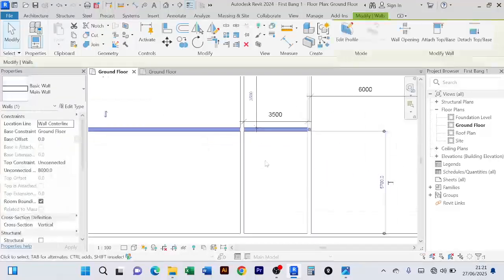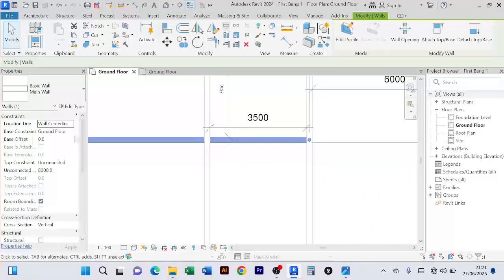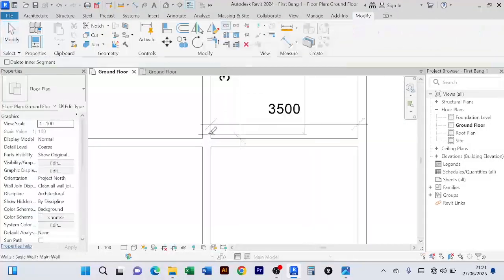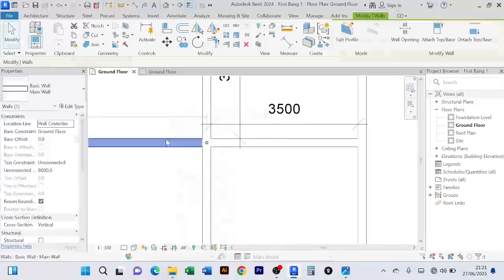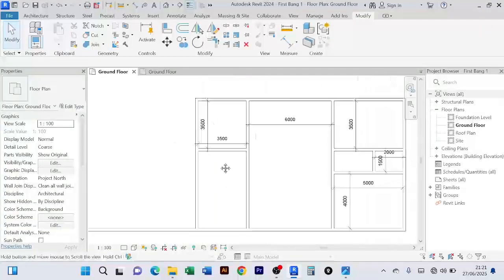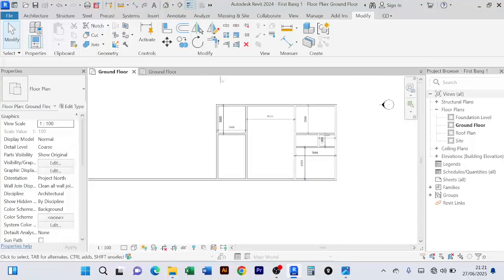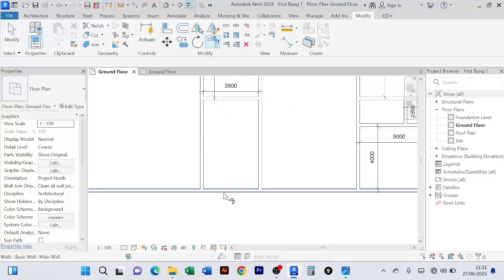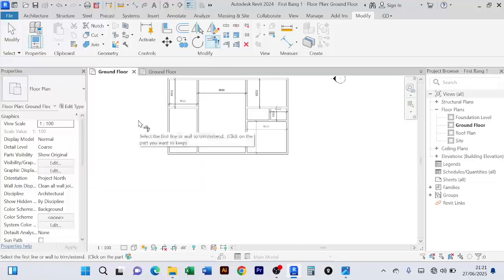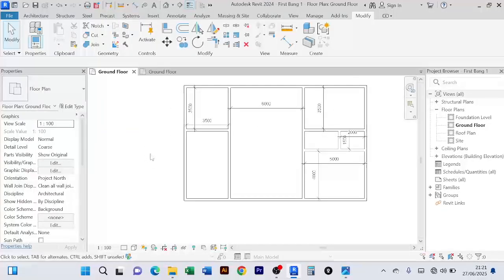Then this one here you can split. Come to the split element, you click that, it will split it, then you delete it off so that you don't have that excess part. Then of course this one can be done with the trim tool, which is the TR. You can do this and do that. See that? Always make sure you escape.